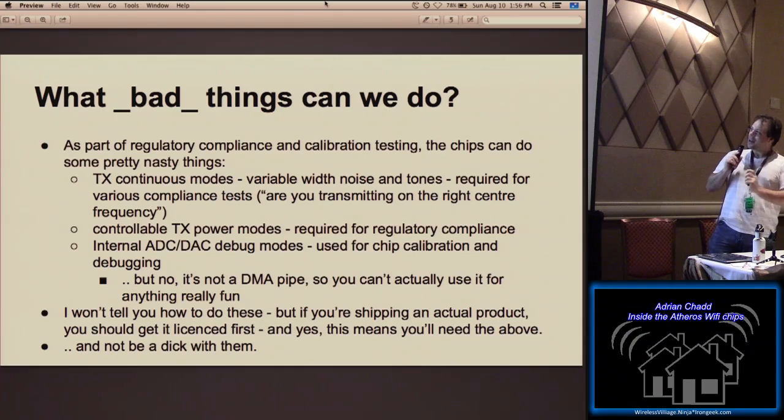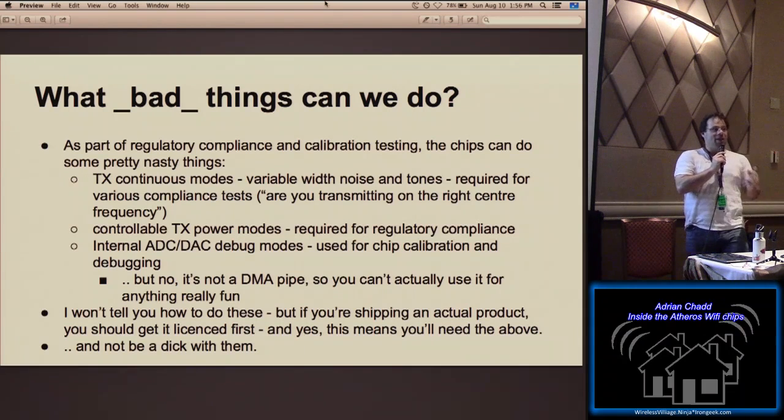You need to know how to do these if you're submitting your equipment for FCC testing. And I'm pretty sure most of the stuff that we buy, where they just take an Atheros NIC and shove it into an existing design, like a board, and make it work, isn't actually being FCC tested. Getting something FCC tested isn't getting an FCC tested NIC. It's getting the enclosure and the antenna tested as part of a product. So they end up having to implement this stuff and then prove it.